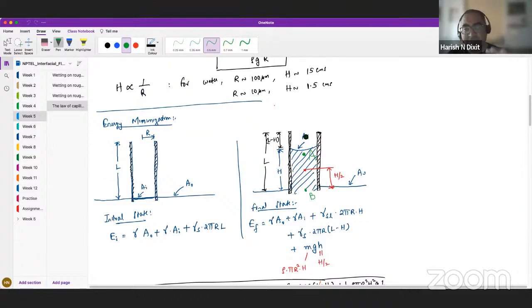See, the atmosphere is trying to push it down. That is P naught. Now you are saying that this particular column, its pressure is slightly lower than what its value would be when it was stationary, because of the very fact that it is moving with a certain speed. Its pressure has reduced. By what factor has it reduced? It has reduced by a factor of rho u squared. U squared in this case is z dot squared. This is only true for a brief moment.